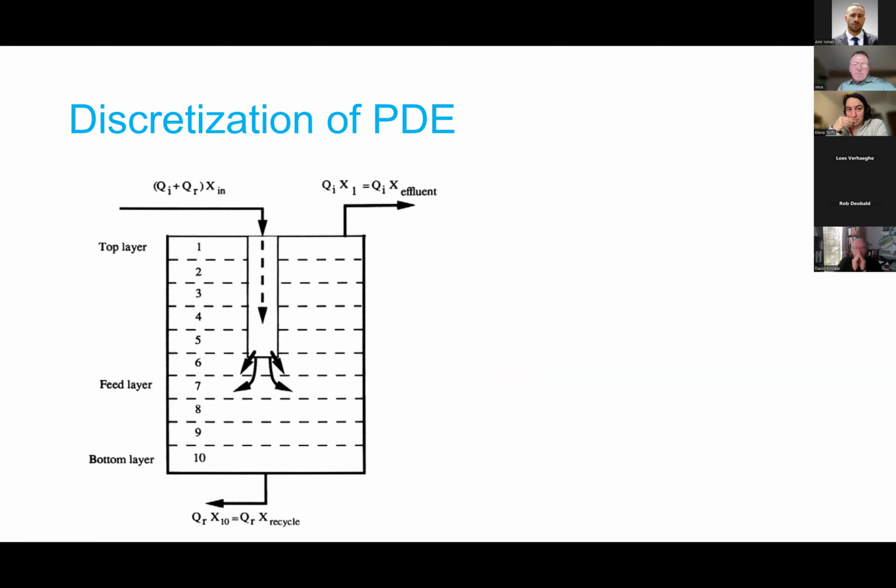So that's one reason why, I'm familiar with the mechanistic modeling of the compression part. But I have to admit, we're using an empirical way of doing it. It's essentially just slowing down the hindered settling velocity, which is what the compression function would do, but it's using a third exponential. So now it's a triple exponential equation that I guess most of these commercial packages use.